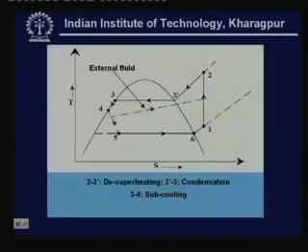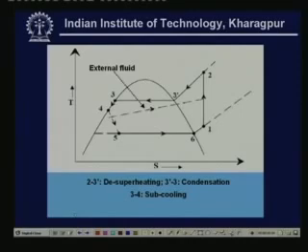You can see here the refrigeration cycle on a T-S diagram. Here the condensation process is shown by 3'-3, and the heat rejection in the condenser is shown by the process 2-4. This heat rejection consists of 3 different stages. The first stage, that is 2 to 3', is what is known as your desuperheating zone, during which the pressure remains constant, but the temperature varies from T2 to T3', which is nothing but the saturated temperature corresponding to the condenser pressure.